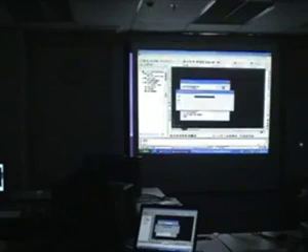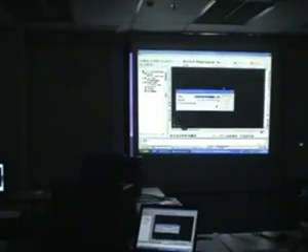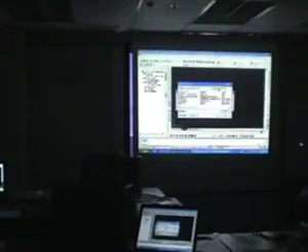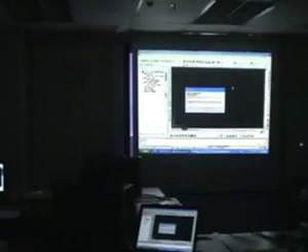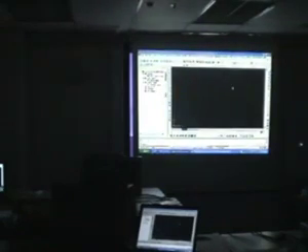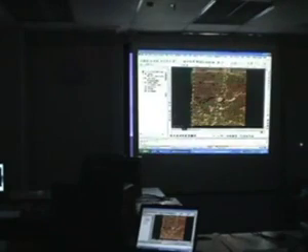But for this particular case, it's really easy. So we're just going to use ENZ, comma delimited. I'm going to browse to that file. And I'm going to add this to a point group called OGL, for original ground level. I'm just going to click OK. And what it's doing now is converting that text file into Autodesk Land Desktop points. I'm just going to zoom in to show you the points.